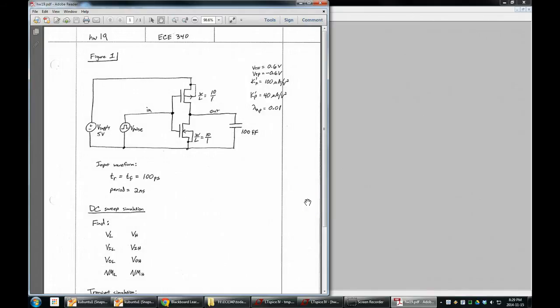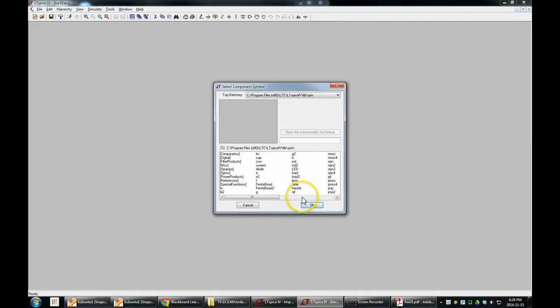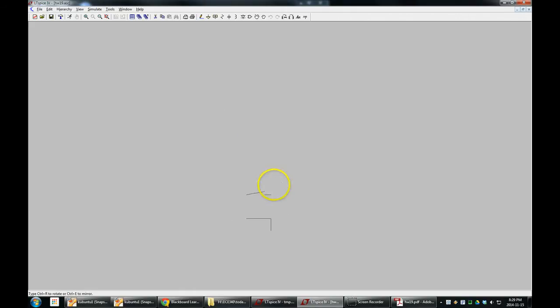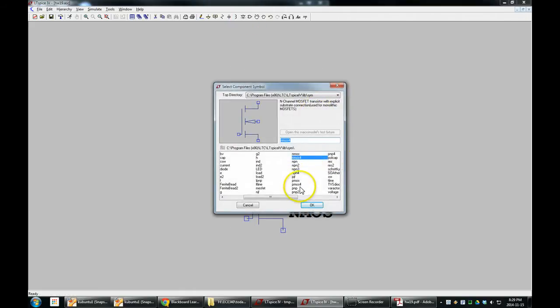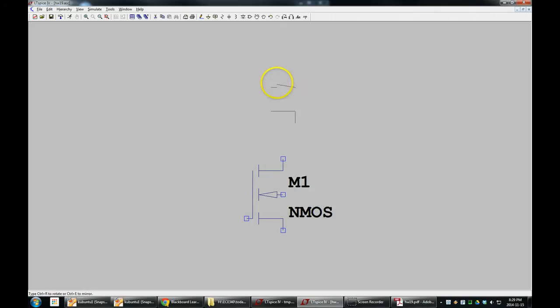Alright, in this video we're going to work on homework 19, or at least get it started. You've already watched the other one to work on this. These transistors are about the same. So here we go. Let's make an NMOS transistor. Start doing homework 19. NMOS 4 is what we need. Let's throw down a PMOS 4 transistor, and then we'll make our inverter from here.